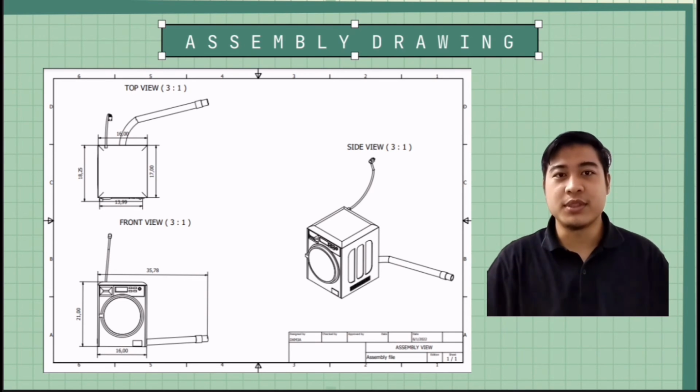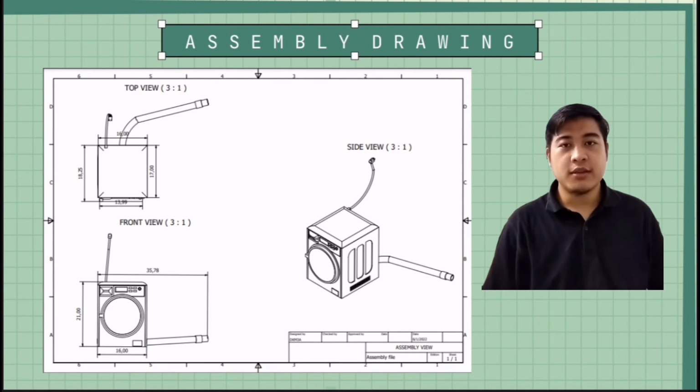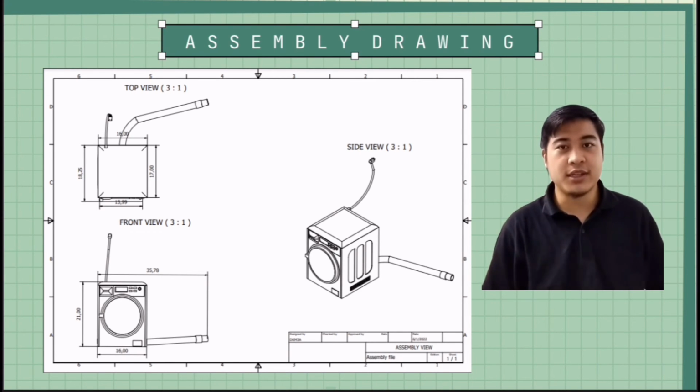After that, we set up the scale as a 3:1 ratio. Then we create the 2 sections, section A and section B, so that we are able to put dimensions on the drawing and make other people understand our drawing dimensions easily. Moreover, we can create another side part of the drawing that we want to display as short next to the section A view. To make a dimension, we can just click the baseline and click every vertical side so